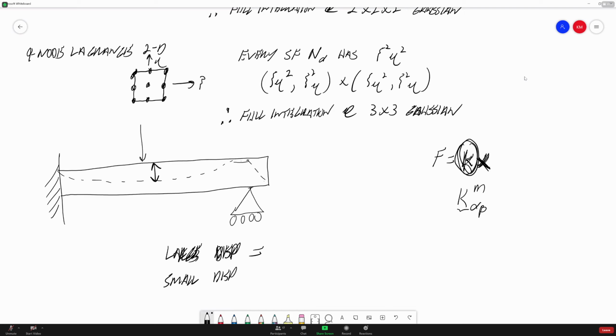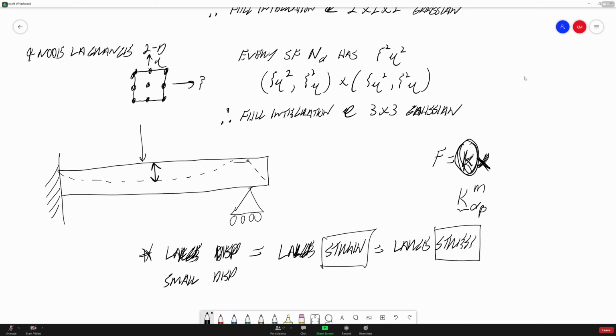So a large displacement will yield a large strain and a large stress, versus this is going to give you small, right? So if you do a calculation and your displacement is bigger than what you would get from a closed form solution, this would be considered conservative because it's going to yield a higher stress, a higher strain. And these are the criteria that you would more than likely base your design decisions on.